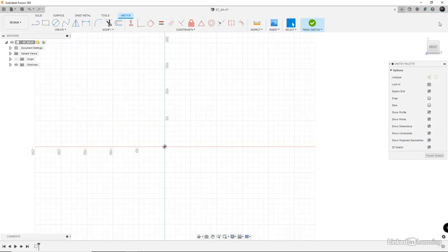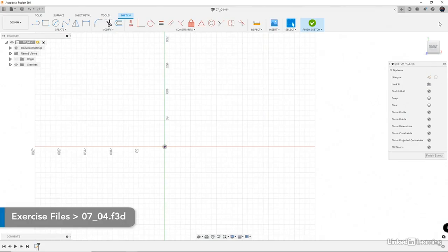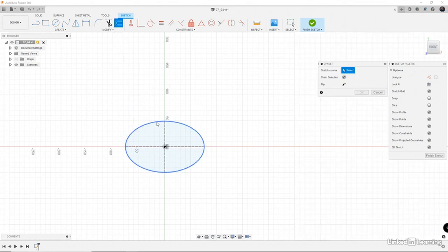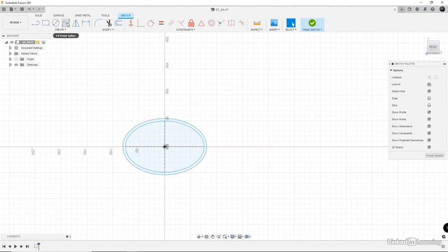Now let's go ahead and build some geometry here. And we're going to build a profile of a face. And then we're going to create a spline so that we can take that profile and drive it along the path of that spline. So let's create an ellipse over here. Let's go to create ellipse and let's just specify, that's good, 98 and by about, let's do around 150. That's fine. And then let's go ahead and do an offset and we'll offset this by 5. That looks good. And then let's go ahead and create a spline and we'll do it right from the center.